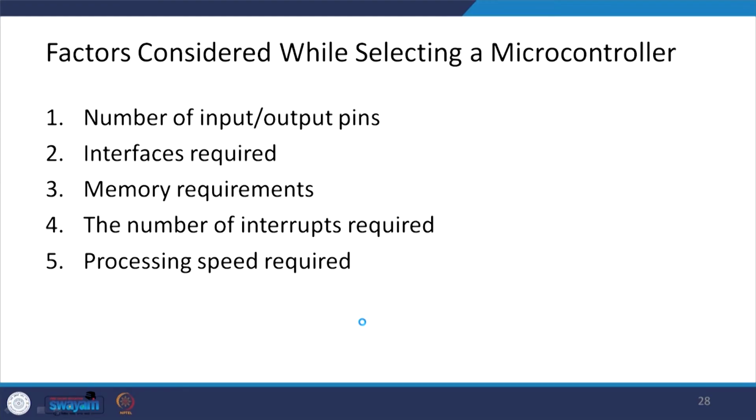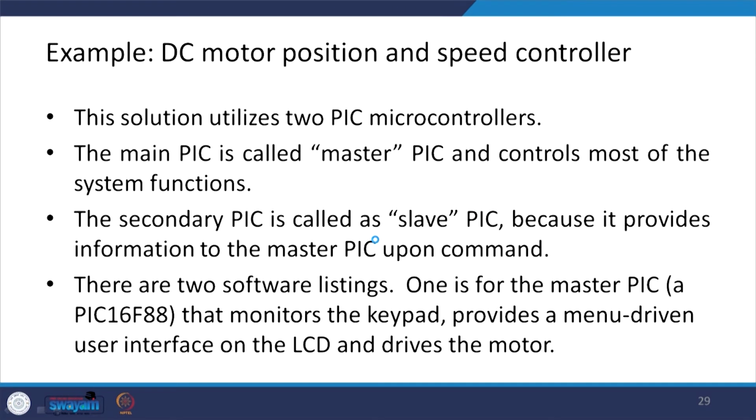Now, factors considered while selecting a microcontroller. Okay. So, the selection of a microcontroller depends on how many input output pins you need, what your interface requirements are, what your memory requirement is, okay, how many interrupts are needed, okay, and what processing speed is needed. So, based on these you can select an appropriate microcontroller for a particular application.